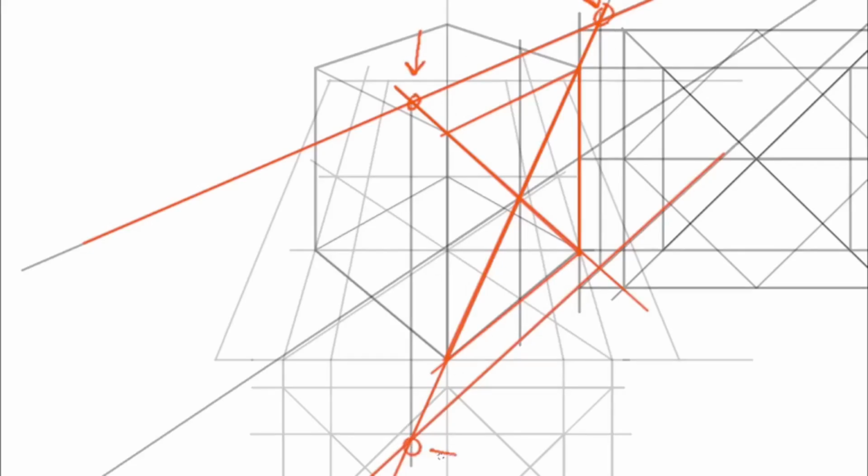Next, the diagonal lines on the right surface of the cube need to be extended as well. At the point these intersect, the new converging lines mark new verticals describing the sides of the bounding box for the new rotated side of the cube. Take the lines from the vertical plan where the rotated square intersects the corresponding bounding box to the converging lines, then transfer them to the new face on the cube.